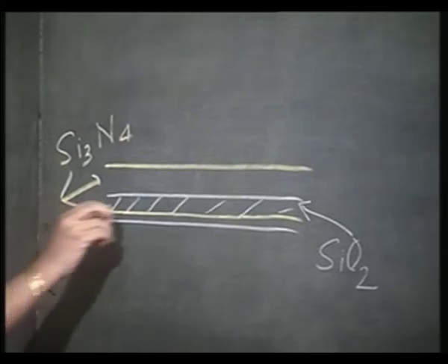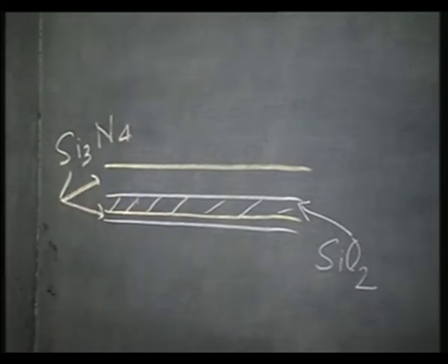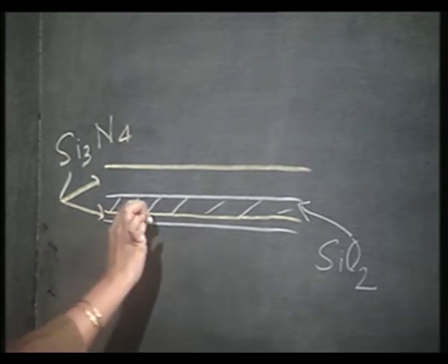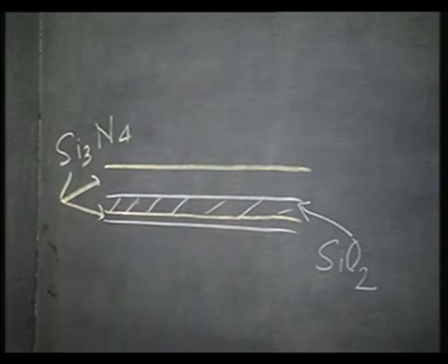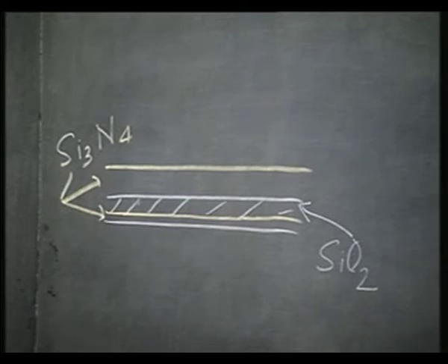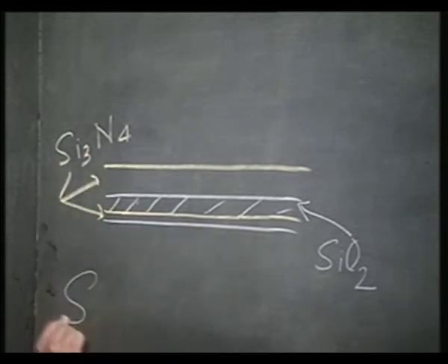So, the stress is still being relieved by the pad oxide layer, but the pad is not in contact with silicon. At the interface, you actually have a very thin silicon nitride layer which will not cause dislocation in the active region, but at the same time it will prevent the oxidation from projecting underneath. So, this is called SILO, sealed interface local oxidation.